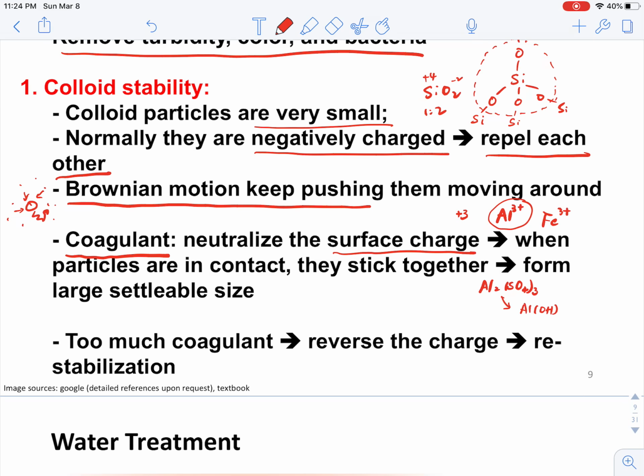And the aluminum hydroxide will tend to carry positive charges. That is because they are mainly affected by these aluminum ions in the water. And then they can start to break down these negatively charged colloids, and then form larger particles. And we call these larger particles flocs.